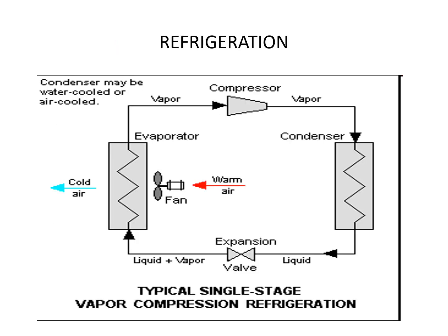This diagram shows the process of refrigeration. As we have discussed, there will be one evaporator, a refrigerator, and then a compressor. The power of the compressor decides the rate of refrigeration, and then there are the condenser and expansion valve. In the evaporator, the refrigerant we are passing will absorb the heat and then change into vapor. It will pass over to the compressor.